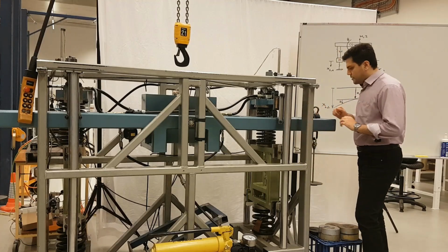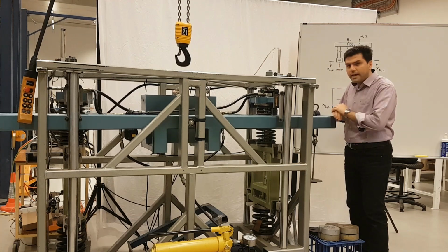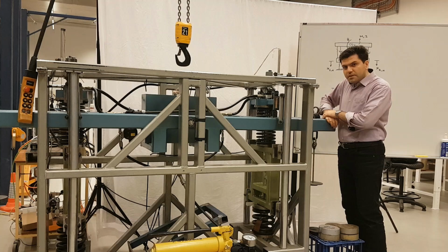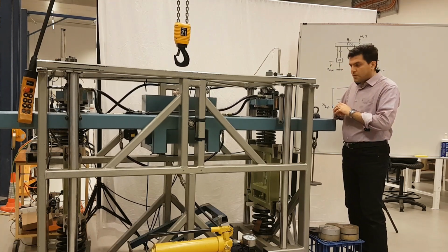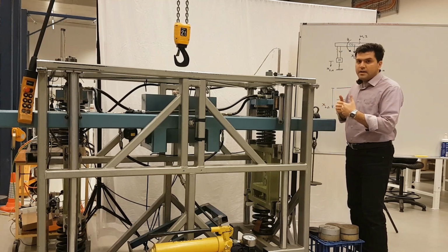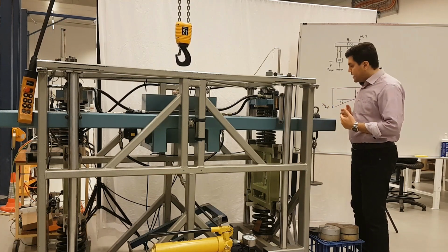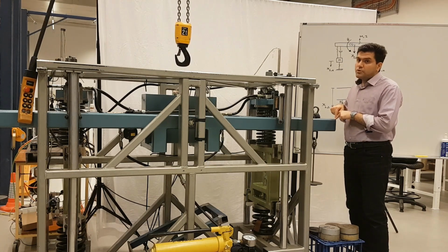Let's just look at the problem from this angle. If I excite the system like that, I give it an initial velocity and displacement. So it starts to vibrate freely, so we've got free vibration, and it dampens out quickly. But I excite both bounce and roll modes.